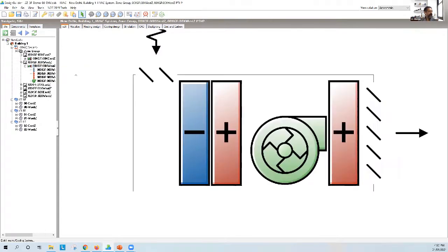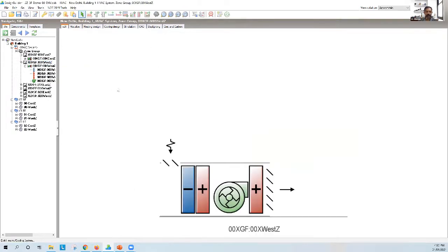But there's one thing here that we haven't looked at. Okay, and if you look at this picture, you can sort of see where I'm coming from. The way this system is working, I recirculate air from the room. I either heat it or cool it. Most of the time I'm cooling it. And then I push it back into the room. Okay. I'm not supplying any outside air. The only outside air that's coming through in this instance is because of infiltration.